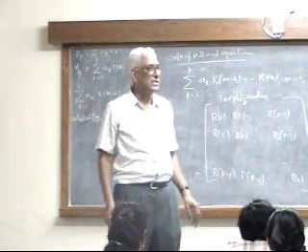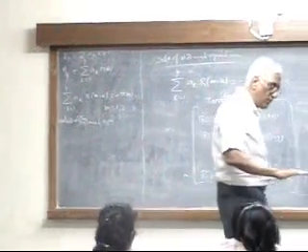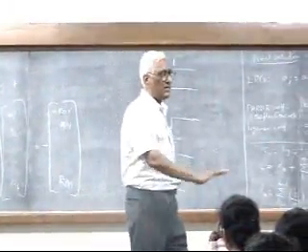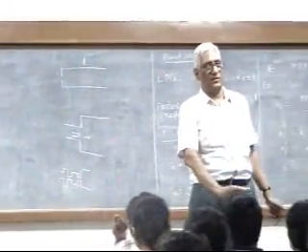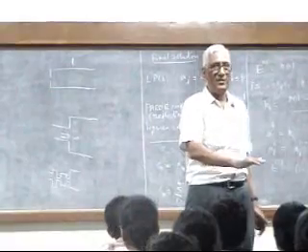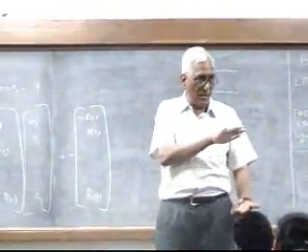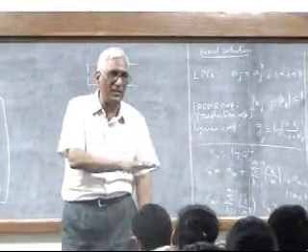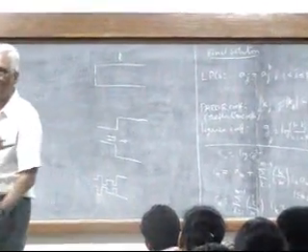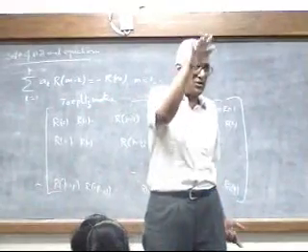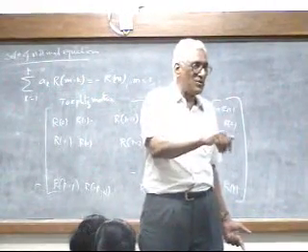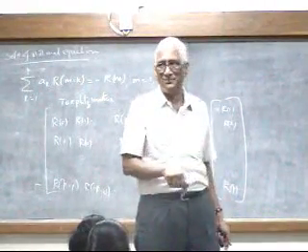And what are those Ks? Those Ks are nothing but the reflection of the different layers of the surface of the earth. You see, if you go down, a certain layer in the soil, or different layers, will be there. Some approximately uniform layer, and then another uniform rocky layer, and some other layer, a waterborne layer like this. So, you assume that there are different layers. So, at each layer there is a reflection.